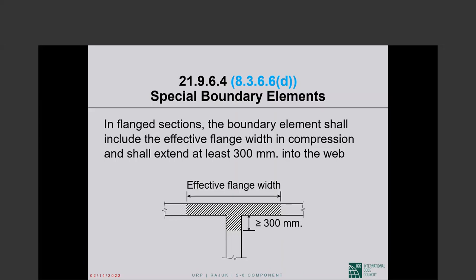Is it necessary to provide a beam at the top of the shear wall? What is this preoccupation with beams? I don't understand. You almost never put a beam on top of a shear wall. Why would you? Typically you will have shear walls and you will have framing outside of the shear walls.